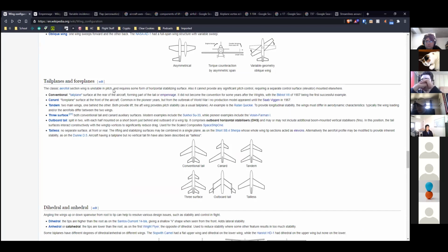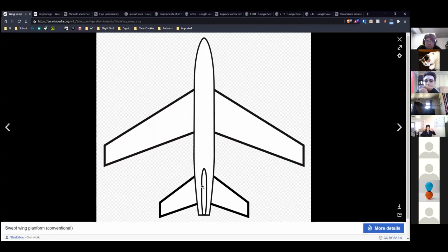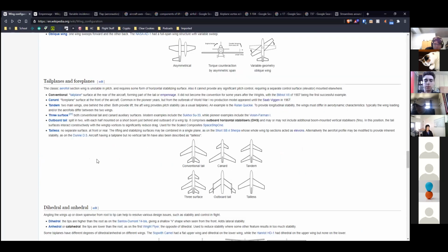Pretty much, this is almost entirely talking about the horizontal tail, because really any plane needs a vertical tail regardless. If you have no vertical tail, the plane can just pivot around the vertical axis and there's no yaw stability. There are very few planes that get away with not having any vertical surfaces at all, and it's because they have some other way to control their yaw.